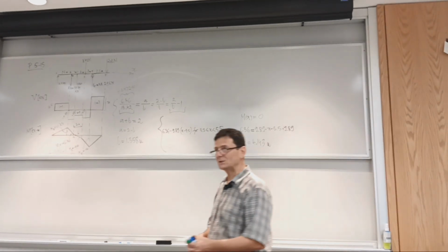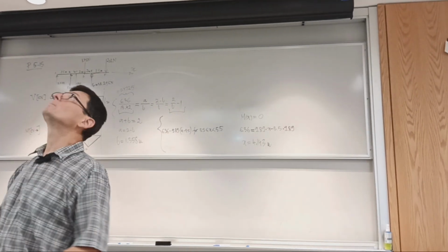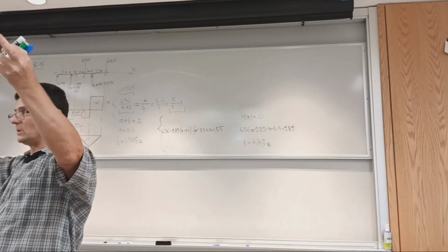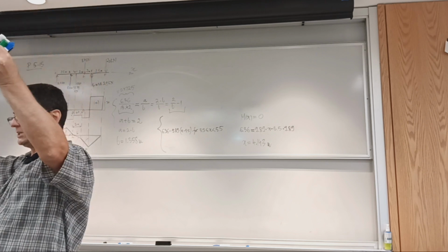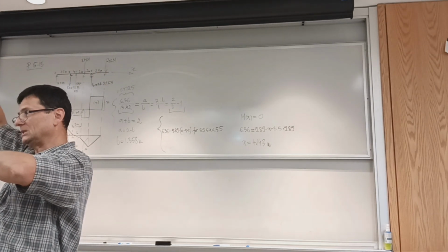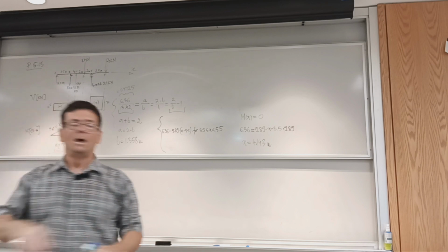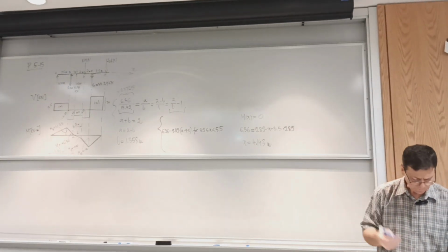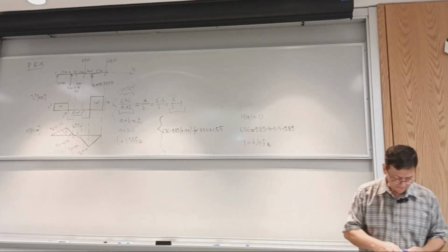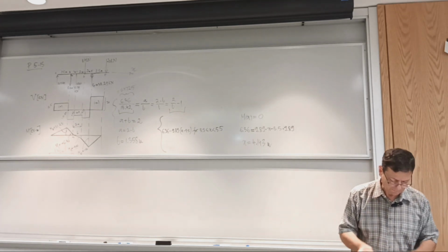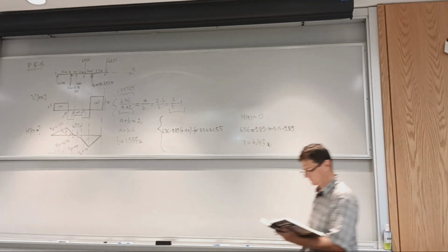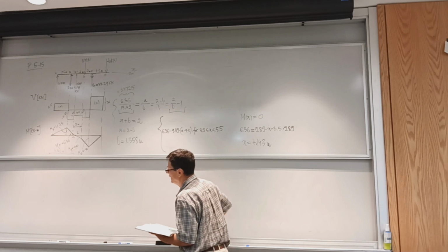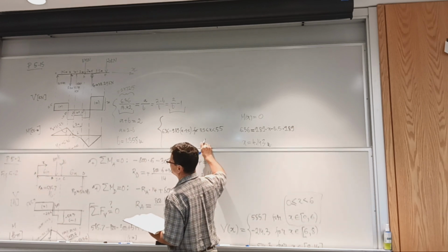If you go to Walmart, for example, I don't know how many of you look for bargains, but look up and you will see frames that look like trapezoids. So they have the supports, but then they change to spread the material to increase the area moment. Anyway, it's not continuous. It's fabricated with trusses, but about the same applies. You increase the area moment of inertia. So yeah, it's a cantilever, and it's having distributed load. So let's see how I go about this.